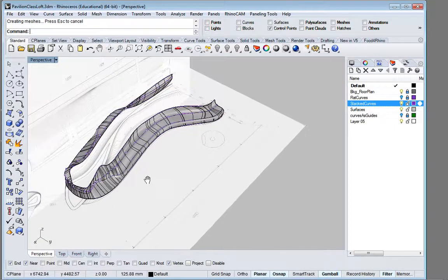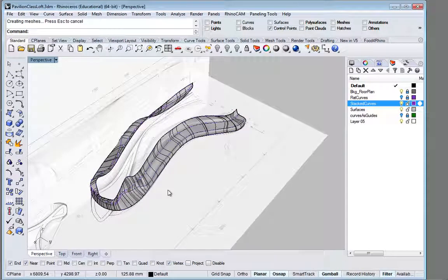So, questions about that? Let's ask any sort of questions. Yeah. Would you recommend using a lot more stacked curves to get a better resolution on lofting? Yes, you can, but there's a danger in that too. The important thing to start off with is to try to get those curves that you're going to create that loft from more evenly spaced in the X direction, or the Z direction, because if you have some that are tight and some that are far away, that causes some problems.